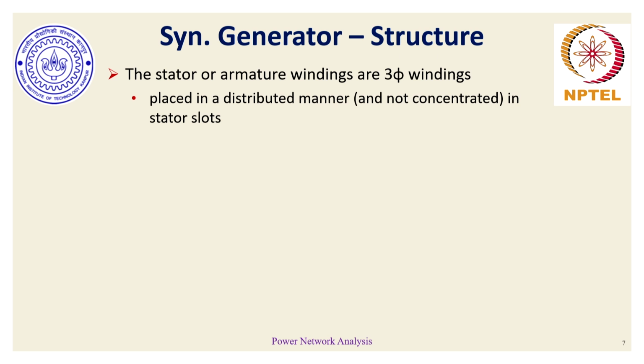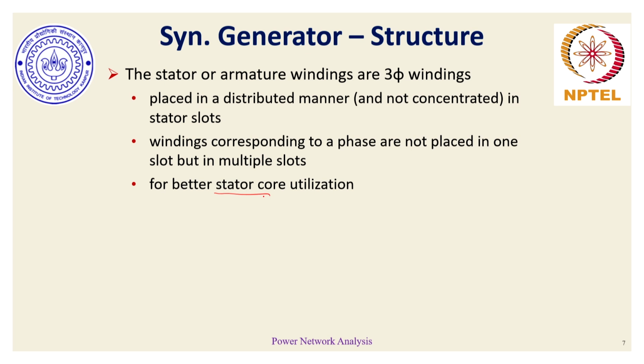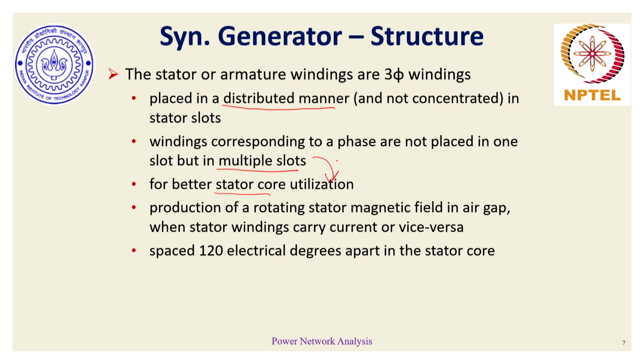for better utilization of the stator in synchronous generators, the windings are often placed in a distributed manner, and windings corresponding to one phase need not be placed in one slot. These windings corresponding to a particular phase can be present in multiple slots so that the core utilization is as high as possible, and it also helps in producing a rotating stator magnetic field in the air gap,